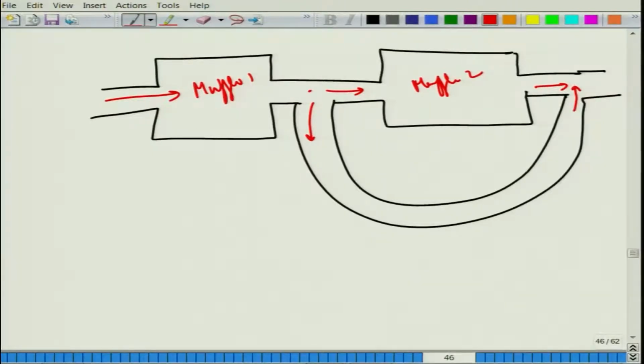So, what is the difference between this system and the one that I had drawn earlier, or just between when you have two mufflers connected without this tube, if this was a solid pipe? What is the difference? Cascading that was used previously now cannot be done, because essentially the idea of transfer matrix multiplication or cascading is really that the wave propagation happens in one direction, and you can just multiply out the matrices to relate things from upstream to downstream.